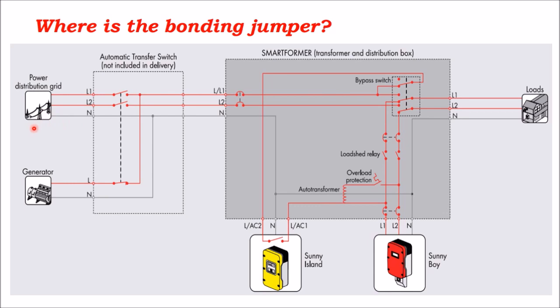Well, it can be at the transformer, up here on the power grid. That could be connected to ground. Or you could have a separate neutral for the power grid and the generator, and you switch between the two, but you're always connected to one or the other. On an automatic transfer switch, you would need to be able to reference both to be able to run the switch.